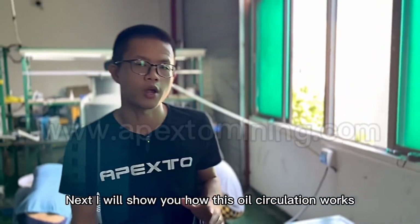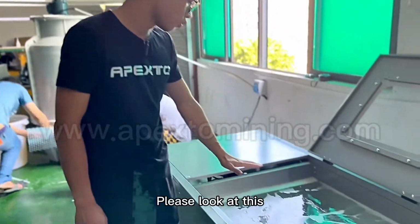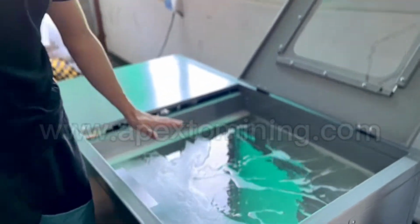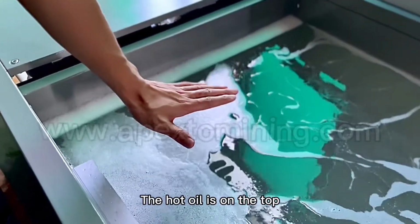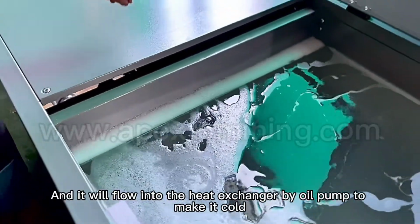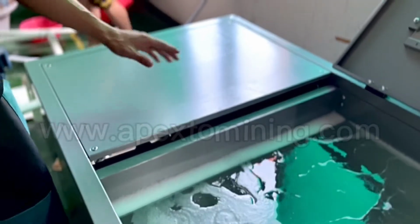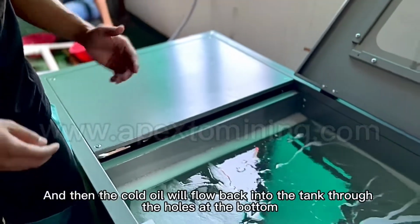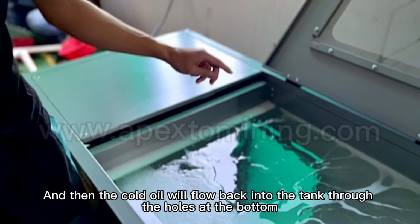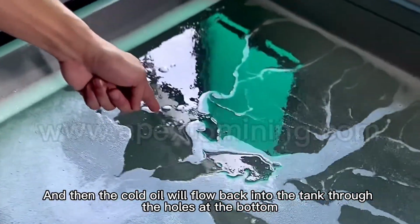Next, I will show you how this oil circulation works. Please look at this. The hot oil is on the top, and it will flow into the heat exchanger by oil pump to make it cold. And then the cold oil will flow back into the tank through the holes at the bottom.